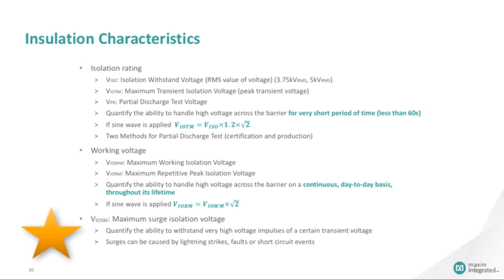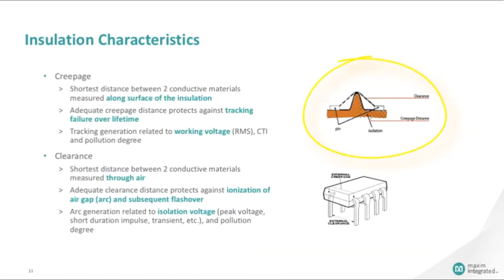As per IEC and VDE standards, an isolator claiming a certain VIO-SM must pass the surge test at a peak voltage of 1.3 times VIO-SM for basic isolation and 1.6 times VIO-SM for reinforced isolation. An isolator can be called reinforced at the component level only if it passes the surge test at a level greater than 10 kilovolts. Creepage is defined as the shortest distance between two conductive materials, measured along the surface of